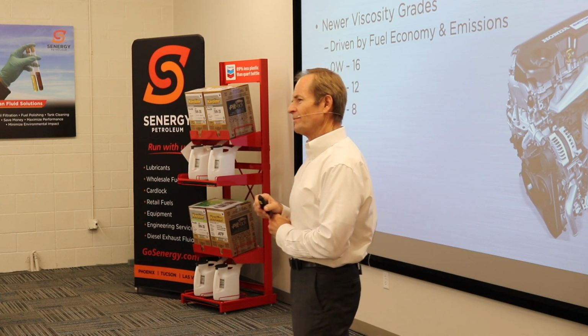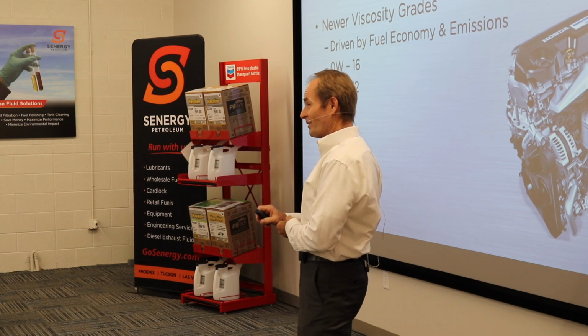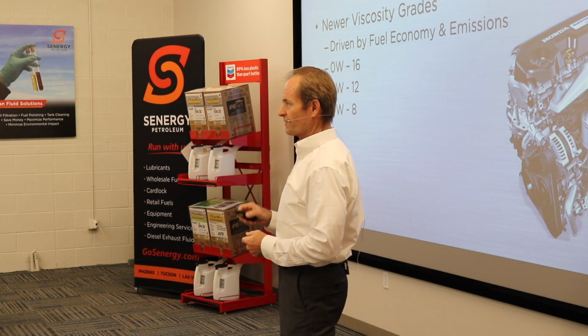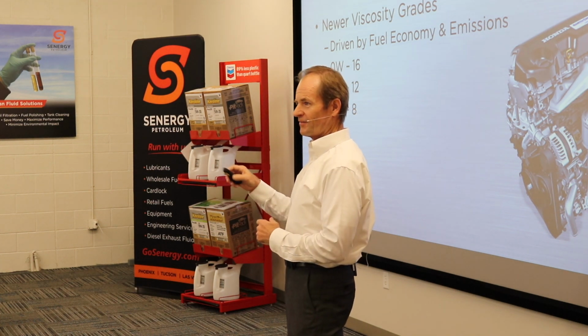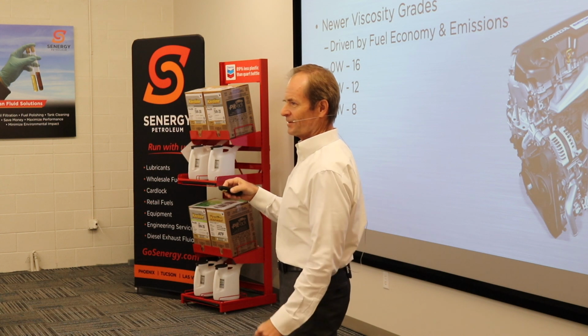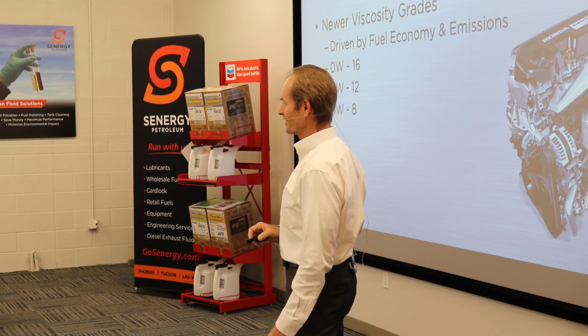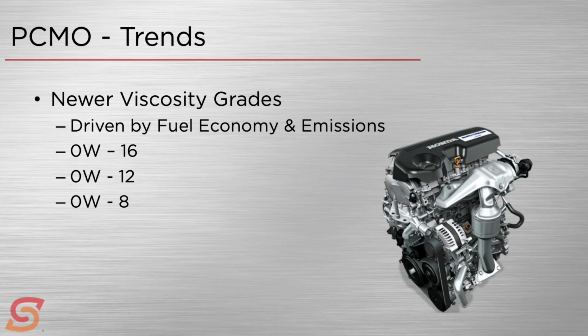Do you know how thick a 0W8 oil is? Okay. 0W8 oil is of the same viscosity as number 4 fuel oil. Now, diesel fuel is number 2 fuel oil, so it's a little bit heavier than diesel fuel, but not much. All right? Think of that, not much heavier than diesel fuel, and that's an engine oil protecting an engine. Pretty amazing stuff. And of course, yeah, driven by fuel economy and emissions.